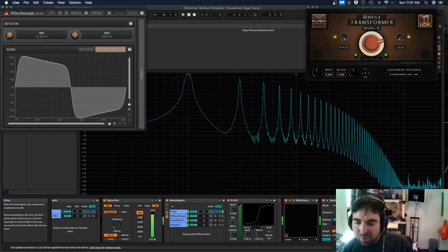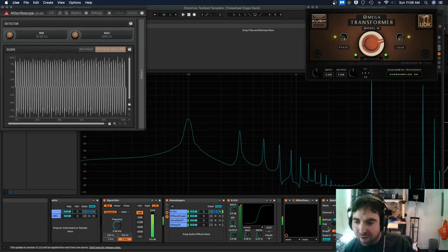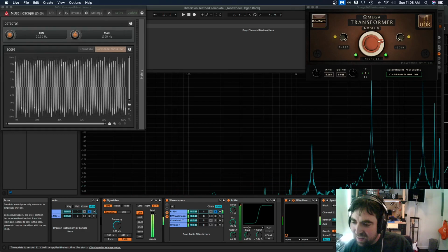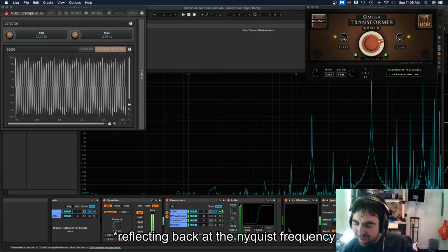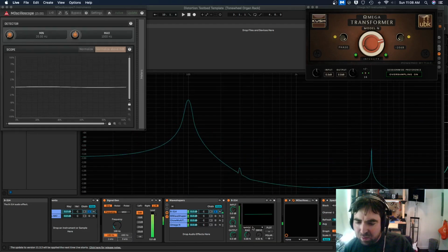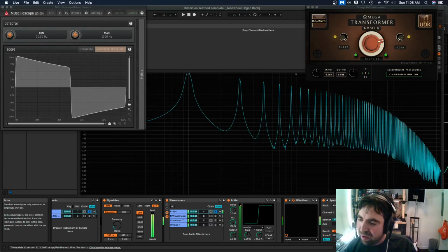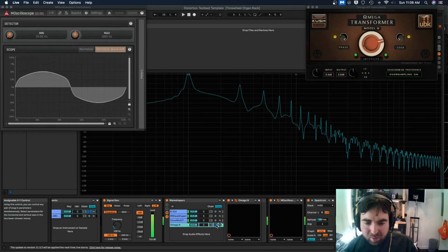I still use oversampling because, say you have, instead of 100 hertz, 5 kilohertz. You can see if you have any sort of high amplitude, high frequency component, you're going to get aliasing. I think this is with 4 times oversampling as well, but you can see the peaks folding out again. Even without oversampling, tanh is pretty well controlled compared to some other wave shaping algorithms. So let's go back to omega n.